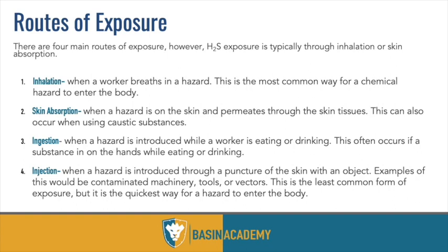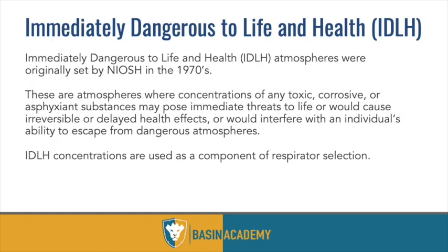IDLH. So I mentioned this before. IDLH, it's not an arbitrary number, but it's a number along a range of a toxin from 0 to 100%, right? Where exposure at that level will cause permanent, irreversible damage to some extent to your body. Whether it damages a little bit of tissue, burns out some nerve endings in your nose, or scars your lungs a little bit, there's permanent, irreversible damage at the IDLH level.